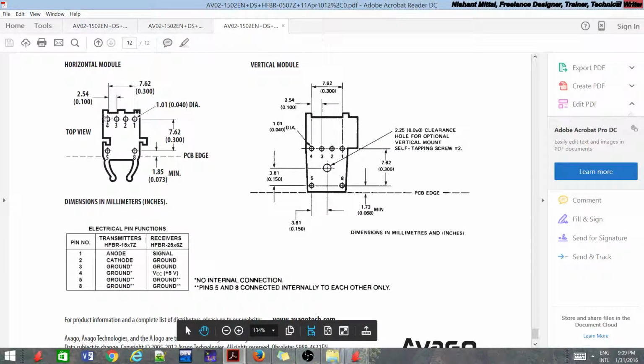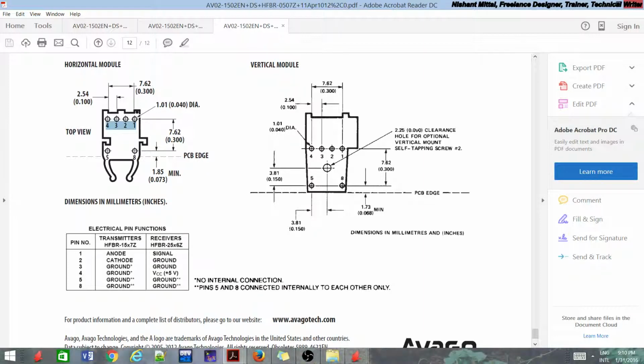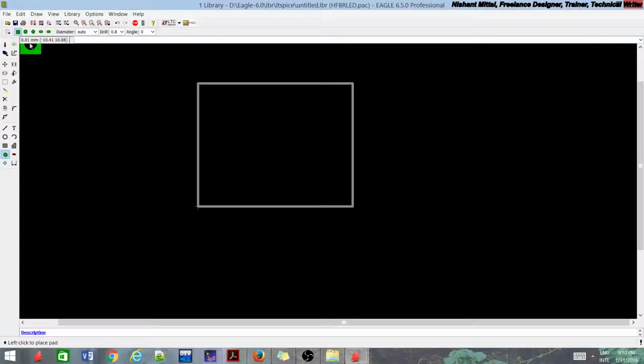In this it has 4 holes over here and 2 holes for drilling over here, or 2 pads and 4 pads over here. Generally these pads should be made equidistant, and many times it is done with intuition. So let's make a round. Generally you either take a round or you take a hexagon. I prefer hexagon because it looks pretty decent while routing.